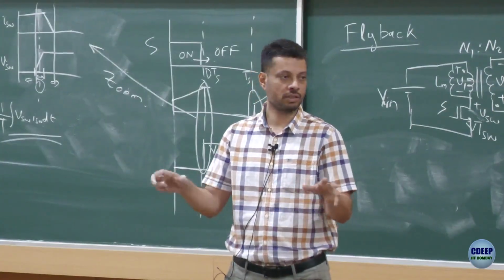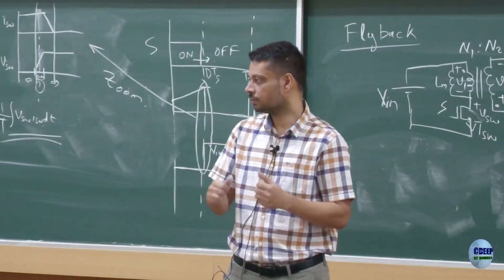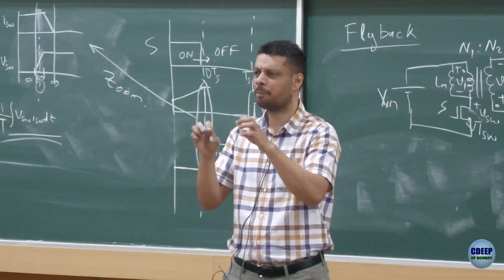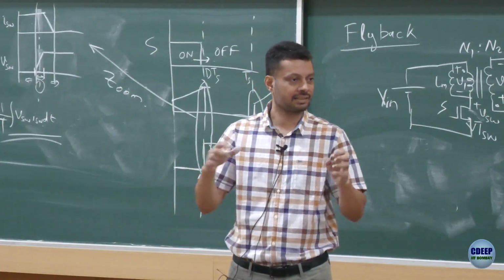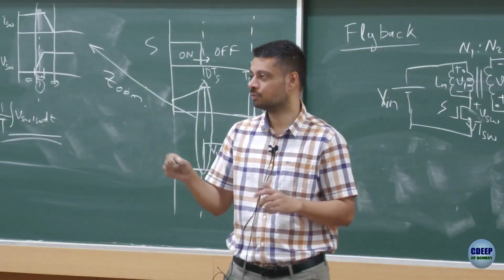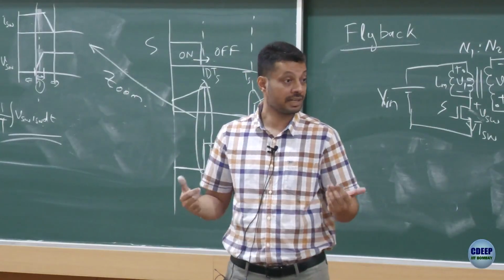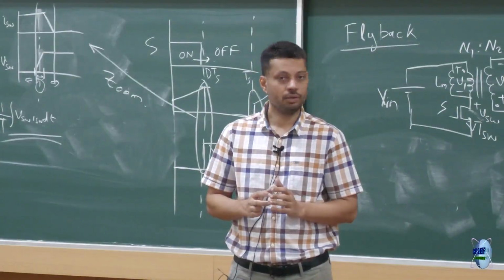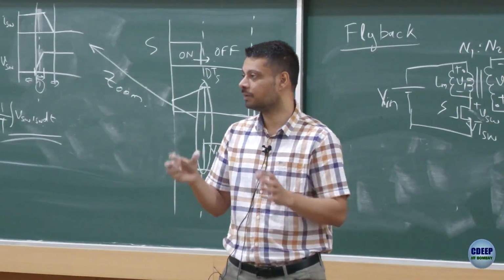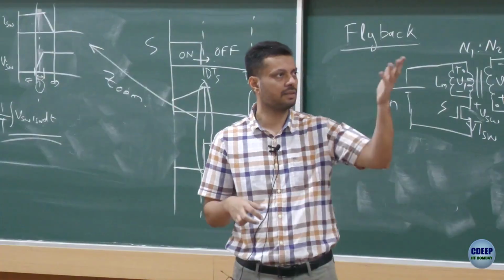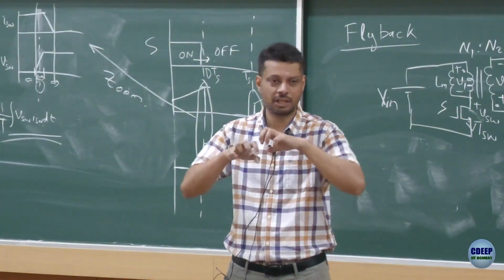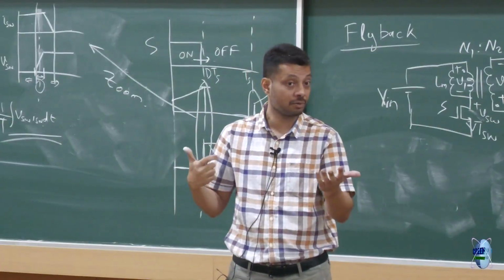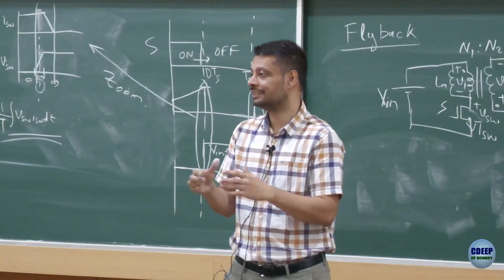That would have some motors, that would have some microcontroller sitting there. Microcontroller would require 3 volt supply for it to operate. You may have some op amps, or some comparator circuits, or some logic circuits which would require 5 volt, or maybe plus minus 12 volt, plus minus 15 volt. So if you see any electronics product, you don't require only 1 volt, you require multiple voltages, and that is true for any product. If you open an air conditioner, for example, internally you would see so many chips. Some chips would require 3 volts, some may require 5 volts, some may require plus minus 12 volt. So there are basically multiple voltage requirements.